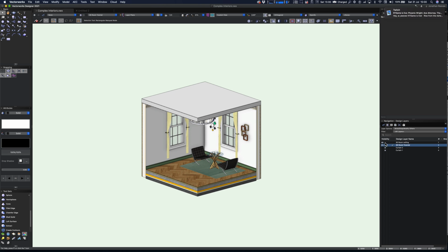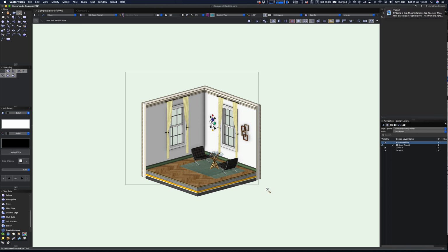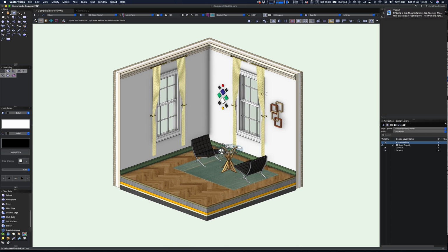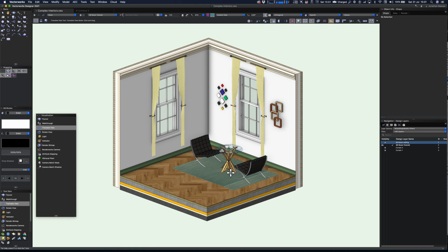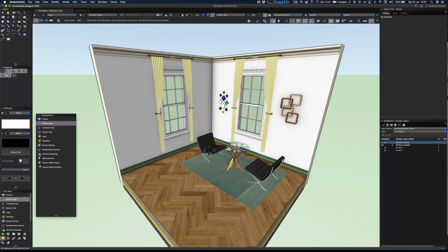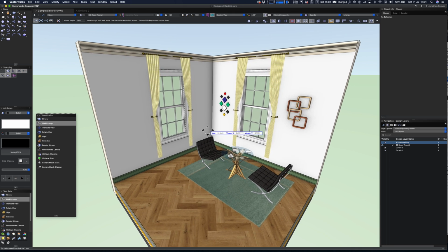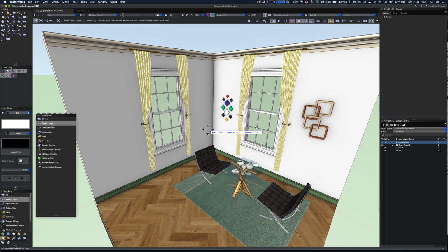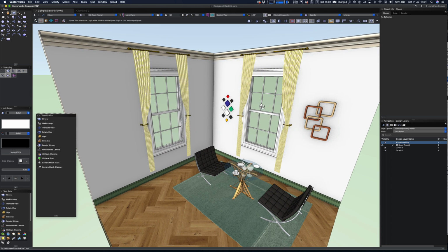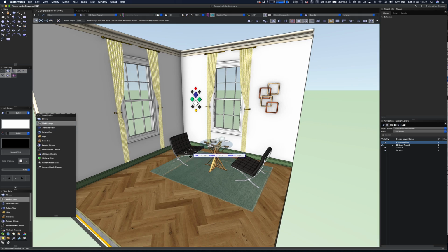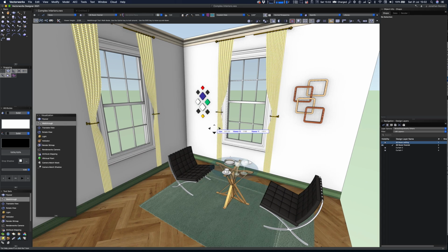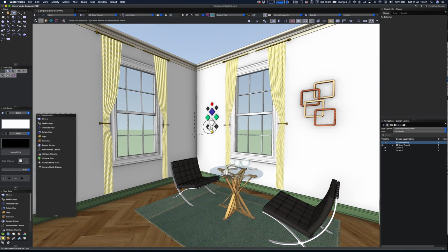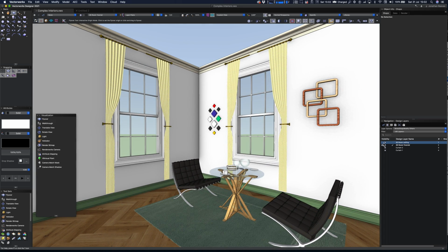Okay, very good. So I'm really starting to feel happy with this now. Now we can start to look at taking some nice views off. So what we'll do is pop it into 3D view. We'll have a little spin around and a walk around. Now when you go to the walk around tool, it will always pop into perspective mode. That's a good way to turn perspective on. You can always turn perspective on if you would like to, just from the top of the mode bar. Okay, so let's have a little walk around, and we'll translate that view to be a really nice view.